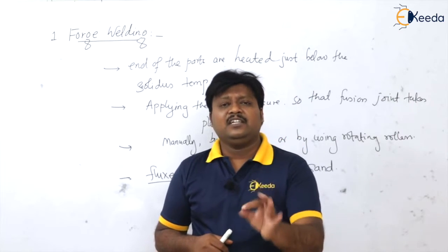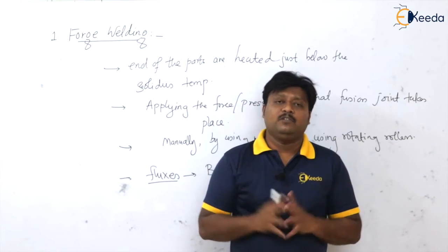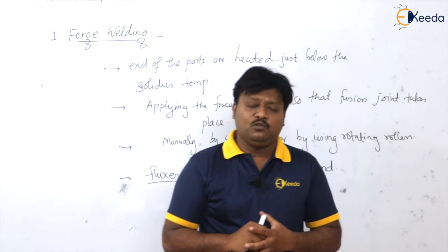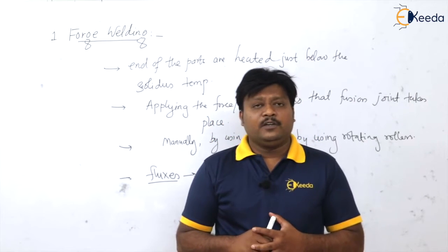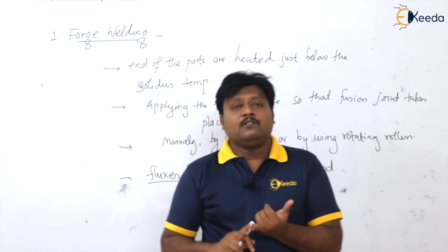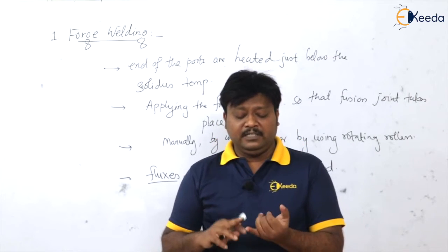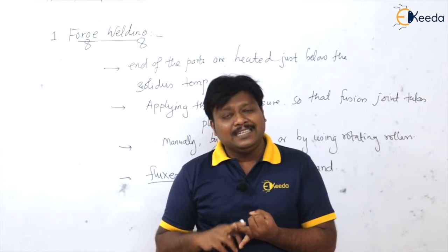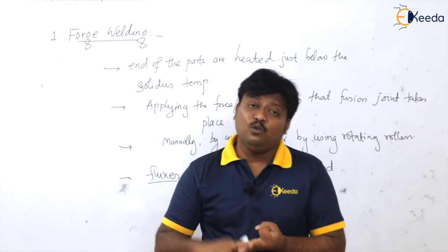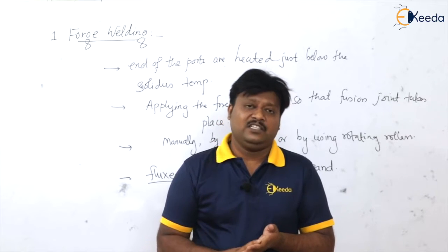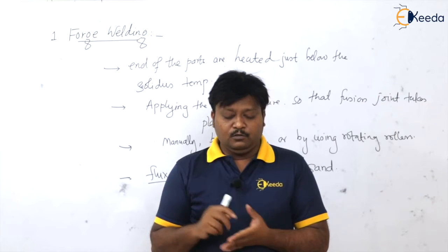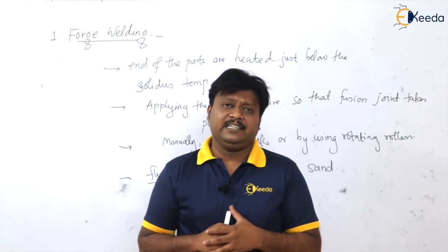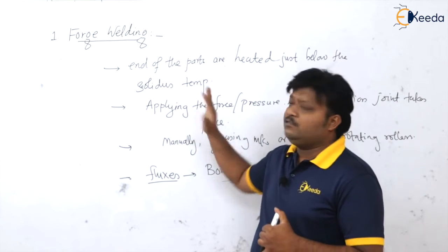In underdeveloped countries they still use this forge welding methodology. So what are the basic limitations? It depends upon the skill of the welder, it is a labor intensive process, it is slow, and it is costly. So it is rarely used in industries nowadays. So this is the forge welding process.